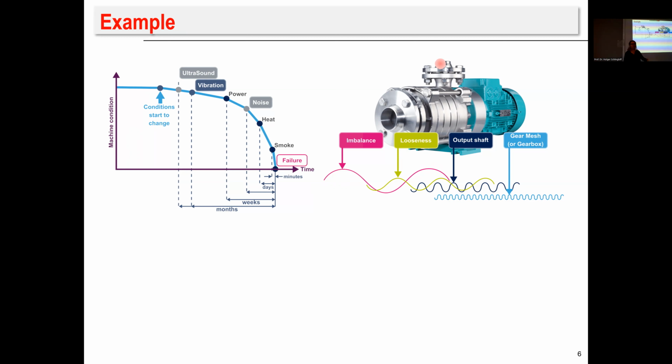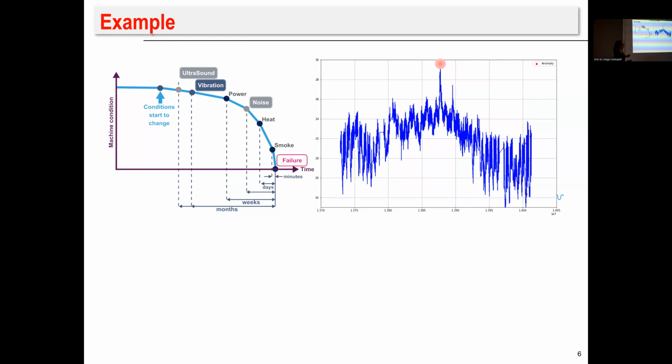Then if it's worse, smoke starts to emit. And in fact, you can detect all of that. If you keep the gearbox in a good condition, then you will be able to prevent this all from happening, and you will prevent expensive failures. So what you do is often, via sensors, anomaly detection. And if you experience funny phenomena that are out of the ordinary, so outliers, then it's time to take action.